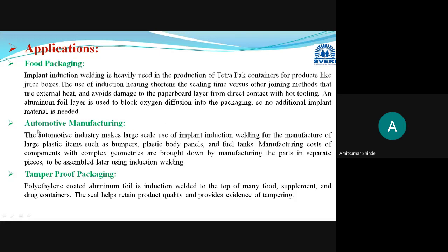Then the next application is in the automobile sector, the automobile industry. This implant induction welding is used for manufacturing large plastic items like bumpers and plastic body panels, then different fuel tanks. All these are joined with the help of this implant induction welding.